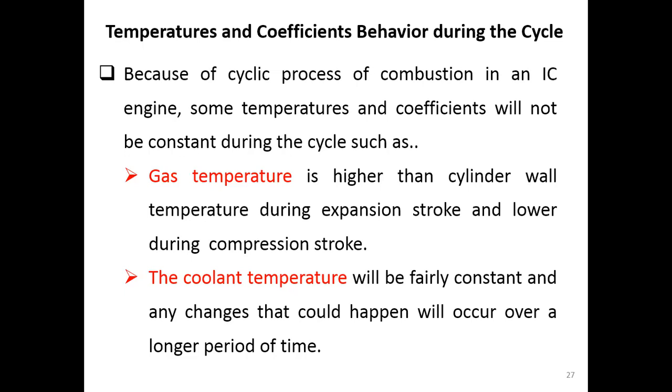So this makes some temperatures and coefficients no longer constant. They change during the cycle. The gas temperature is higher than the cylinder wall temperature during the expansion stroke, and during compression it's lower than the wall. So you see it's different, not constant. The gas temperature itself is sometimes higher, sometimes lower.